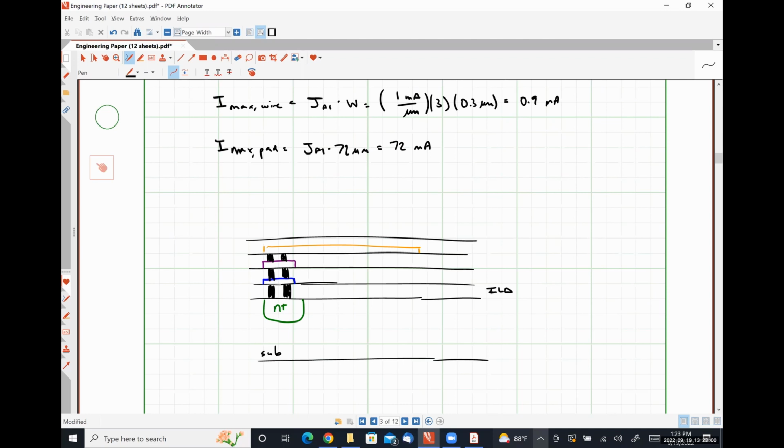Typically speaking, your bonding pad is this big, 72 microns by 72 microns. You can run up a smaller physical dimension piece of metal to touch that, as long as it's large enough to carry the current that you're expecting to carry. The bonding pad's dimensions are purely because you need to be able to physically bond a wire to that. Very, very thin wire, on the order of 50 microns or smaller in diameter, but it is an actual wire that's going to go off to the pins that you have access to when you plug this into a breadboard or something like that, okay?